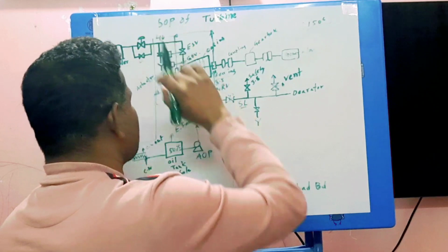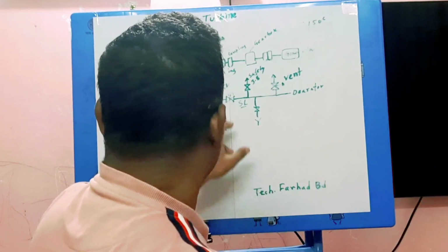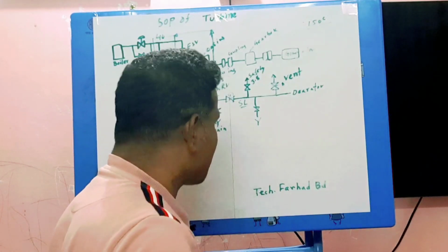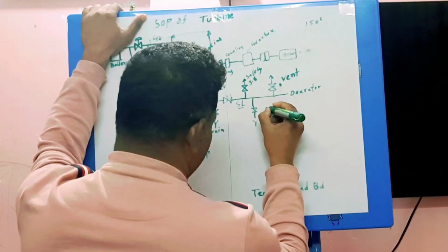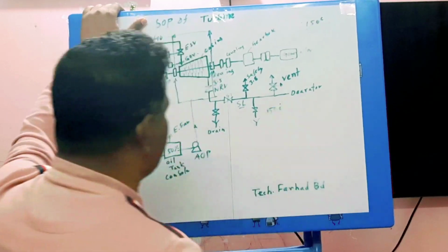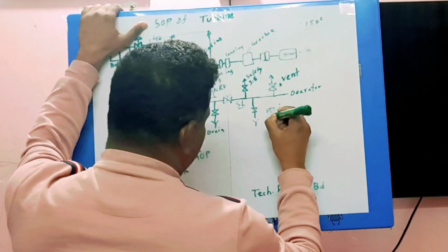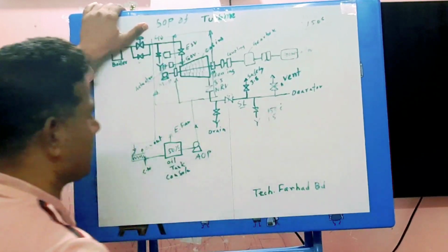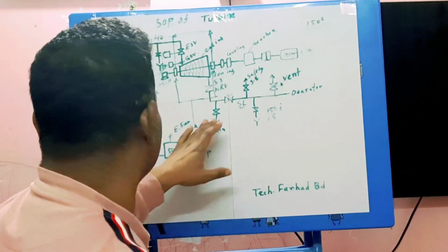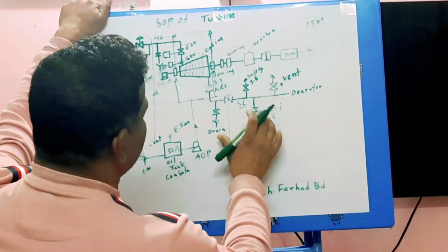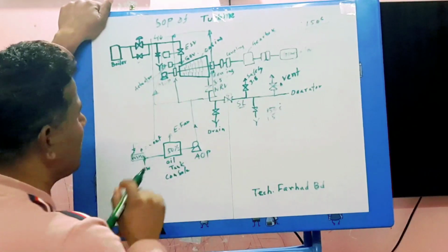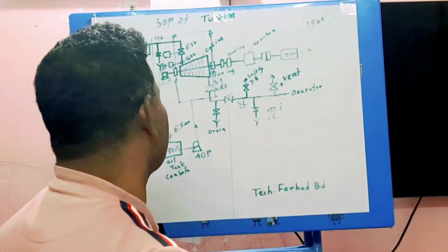Gradually open this bypass valve and increase the SL or low pressure steam line temperature to more than 150 degrees centigrade. When this side temperature reaches 150 degrees centigrade and the pressure 1.5 kg arrives, that time you have to reduce the drain valve. You have to reduce the drain valve slowly. After 20 minutes, you have to close this drain valve. Only the casing drain valve can be kept slightly cracked open.